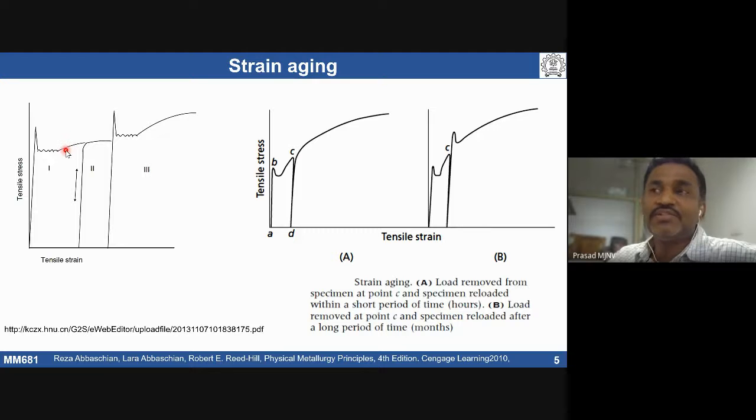Okay, so dislocations can move very fast, and the solute atoms can be unpinned, completely unpinned. So dislocations move at a very fast rate during deformation. Solute atoms may not diffuse at that same rate. So now more and more dislocation density has been generated, but the solutes are sitting randomly. The atmosphere is now completely gone; it's not there that much.